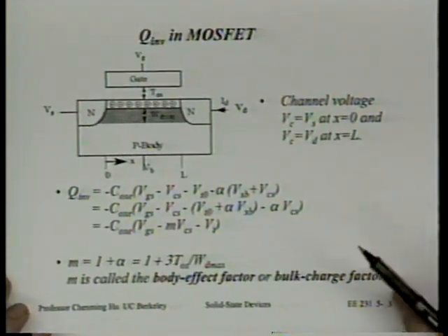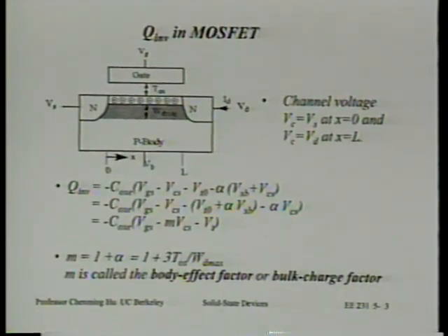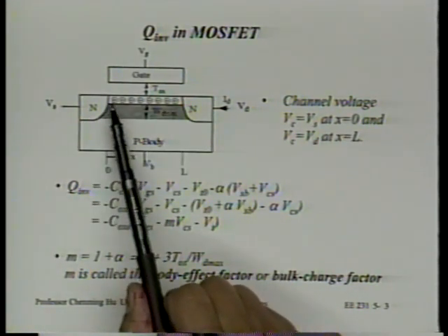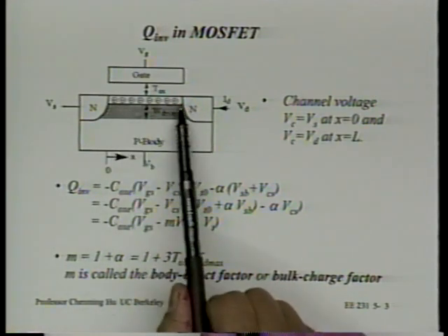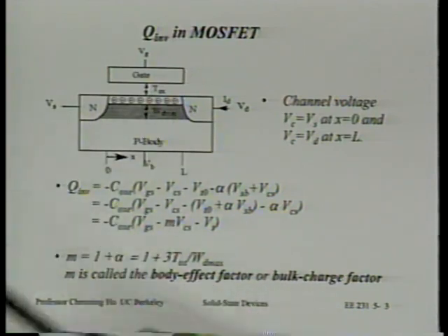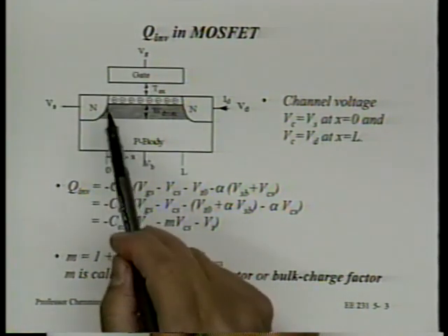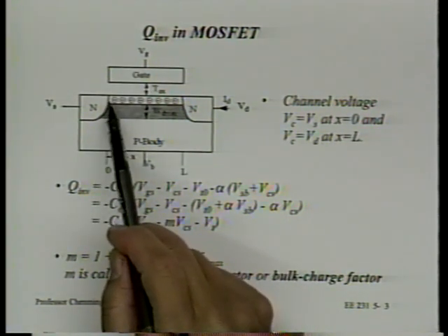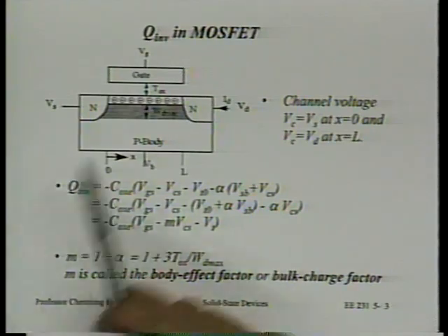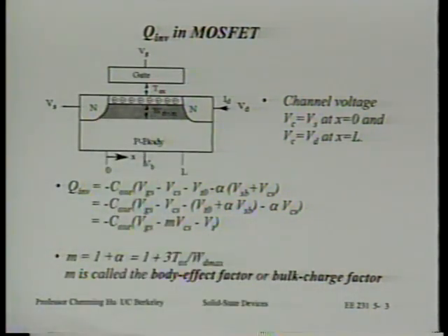All right. Now we'll apply a non-zero VDS. Suppose now we apply a VDS. Again, imagine this inversion layer as a very thin conductive sheet. Now the potential along the inversion layer will no longer be constant. The potential at the source end of the inversion layer is Vs. At the drain end, the potential is Vd. In between, of course, somewhere between Vs and Vd.